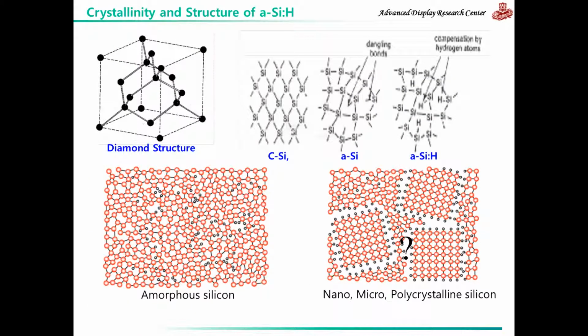So what exactly does it mean to say the silicon is amorphous? Silicon is a four-fold coordinated atom that is normally tetrahedrally bonded to four neighboring silicon atoms, as you can see here in the top left corner. In amorphous silicon, the tetrahedral structure continues. In crystalline silicon, the tetrahedral structure continues over a large range, as you can see here, thus forming a well-ordered structure.